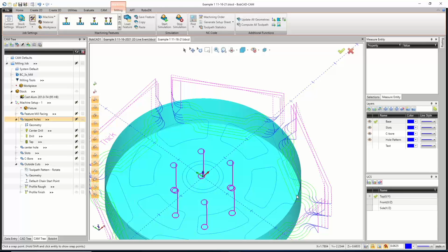And a lot of it comes from the fact that we're using wireframe geometry to define our holes. If we had a solid model and we picked the inner surfaces of the solid model holes, then when we say reselect geometry, it reads the diameter and the depth from that. So the odds of it not making a mistake doing it that way are better. But you'll always have to double check the holes, especially when the origin changes Z positions, it can act kind of weird. So there we go.